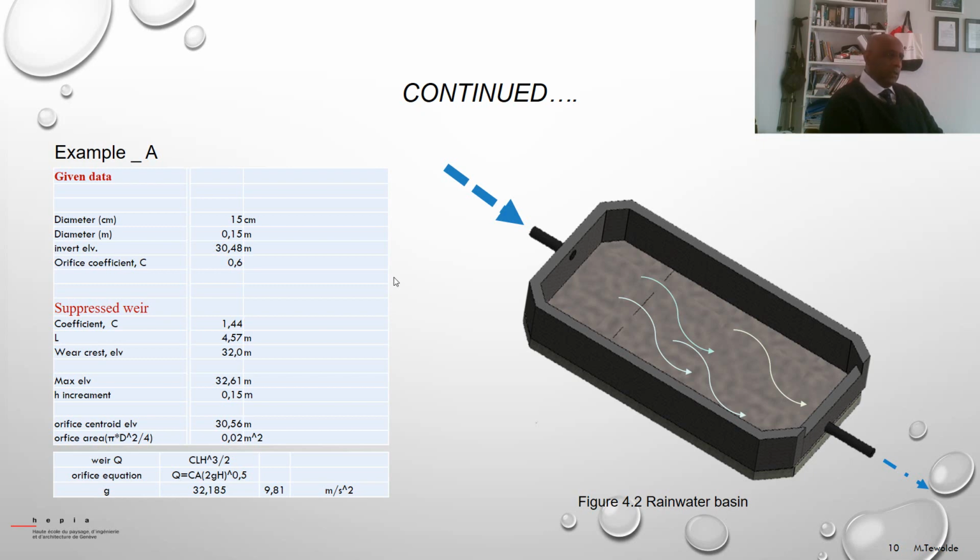And the other is the surface area of the basin. For example, if it is natural, we can do some surveying work and develop a contour and calculate the change in volume in area. You see, there is an area here, an area here.